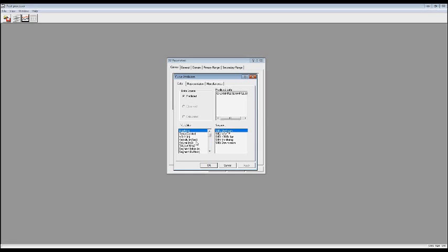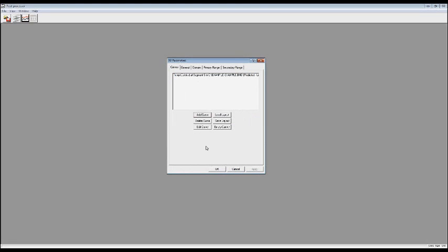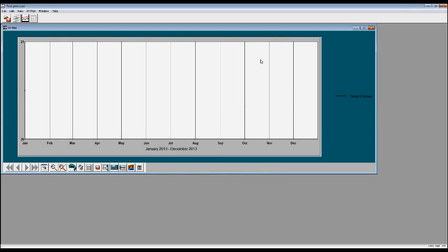So what I'm going to look at first is I'm just going to plot temperature. And I'm going to just plot it at segment 5. And this is basically just going to give us a time series graph of temperature. So I click OK, and there's my graph. And if you recall, under the segment parameters, we set the temperature to 20 degrees. And as we can see in this graph here, it is 20 degrees for the whole year.